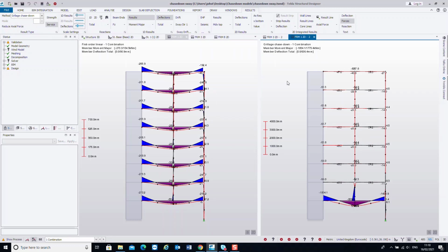During the 3D building analysis, the column nodes will be free to displace vertically. At this location, the connected beams will also be able to displace vertically, leading to bending within the members. The bending resistance of the beams will then contribute to the resisting force in the column, and that additional bending resistance will therefore reduce the axial force within the transfer beams, leading to a smaller moment in our final transfer beam.